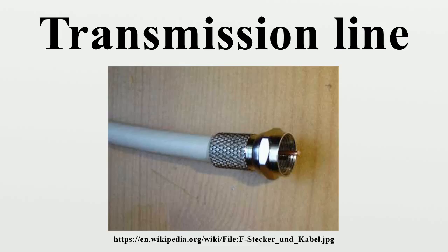Stated another way, the length of the wire is important where the signal includes frequency components with corresponding wavelengths comparable to or less than the length of the wire. A common rule of thumb is that the cable or wire should be treated as a transmission line if the length is greater than 1/10 of the wavelength. At this length, the phase delay and the interference of any reflections on the line become important and can lead to unpredictable behavior in systems which have not been carefully designed using transmission line theory.